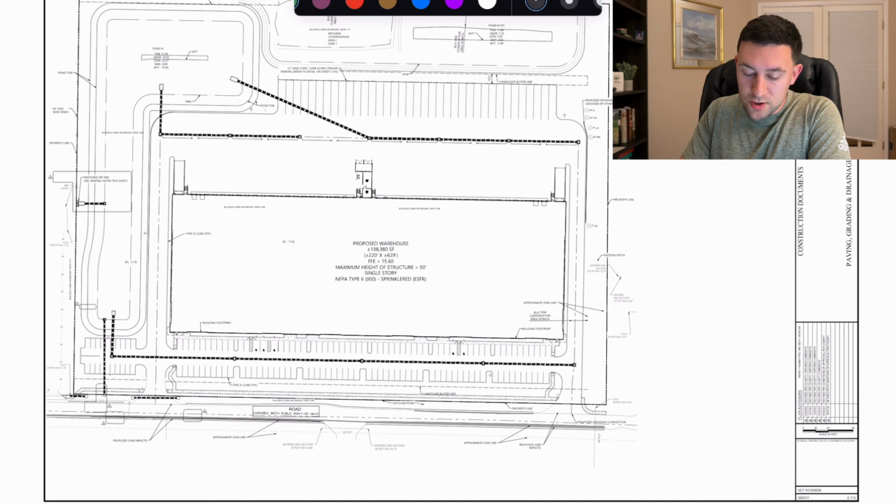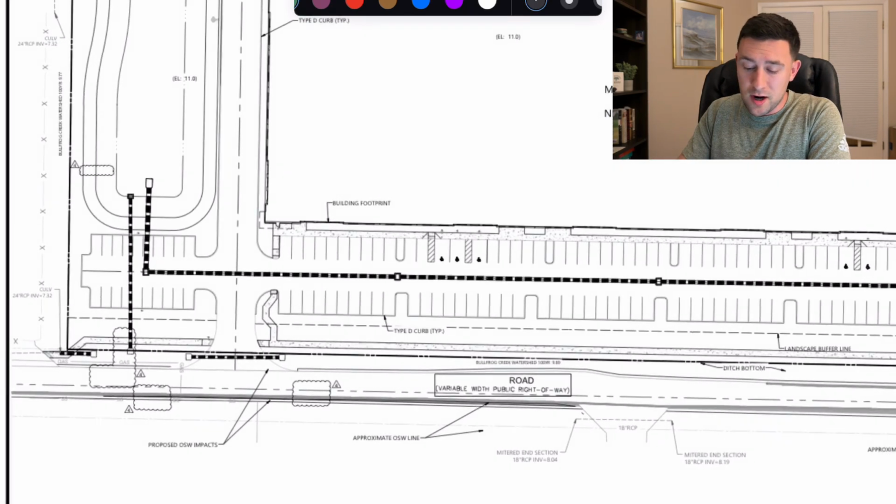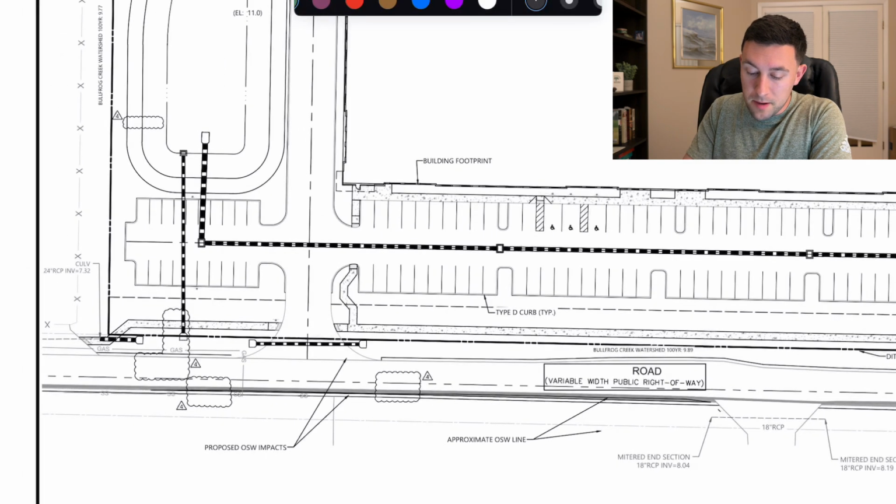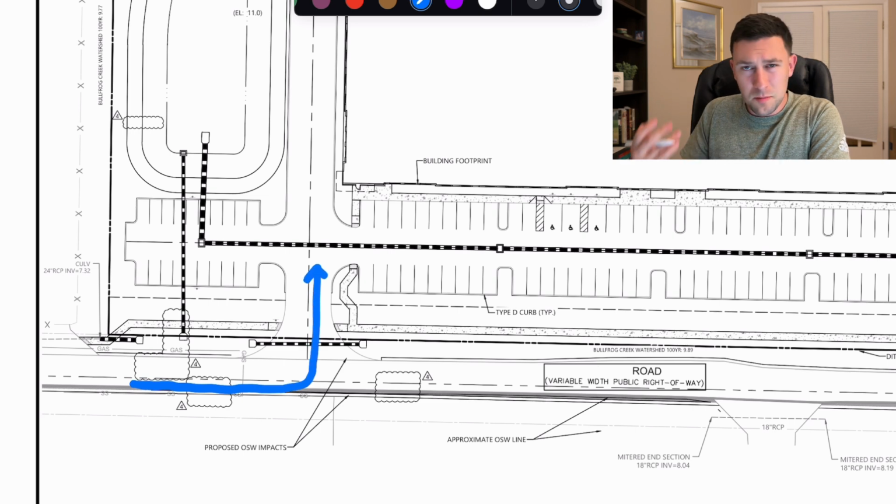The max driveway slope that we're going to have for this property is 10%. We're going to have a lot of truck traffic through here, so we definitely want to minimize the slopes going into this development. So again, if I was a truck turning into this development, I want them feeling less than 10%, going through that. Now, the minimum slope for these pavement areas are 2%.